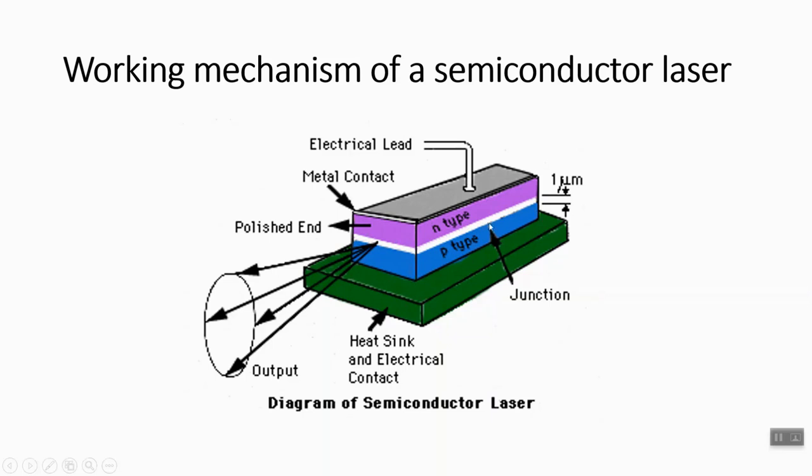In this figure, the white region represents the depletion region. A resonant cavity is formed by just cleaving the junction ends. The light that is trapped is reflected back and forth between the two faces. The other two sides are rough and therefore suppress oscillations in unwanted directions. The active region is a little wider than the depletion region.